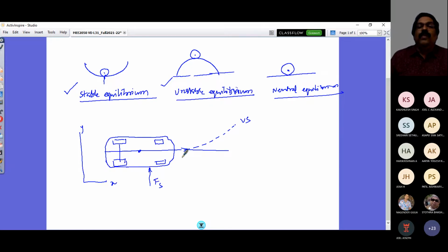The same, if your vehicle is an oversteered vehicle, we know that this would turn into the curvature. So if the side force is acting, it would turn into the disturbance side, and that's the oversteer tendency of a vehicle. At that time, even if you are trying to correct your steering at a particular speed called the critical speed, your vehicle does go into an unstable state, as we have just understood when we started our high speed cornering study.